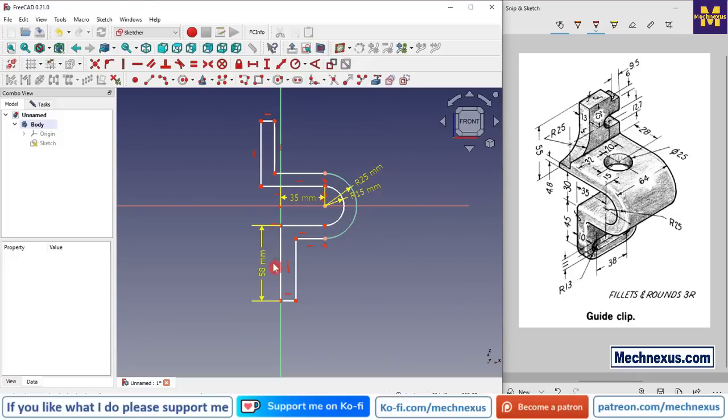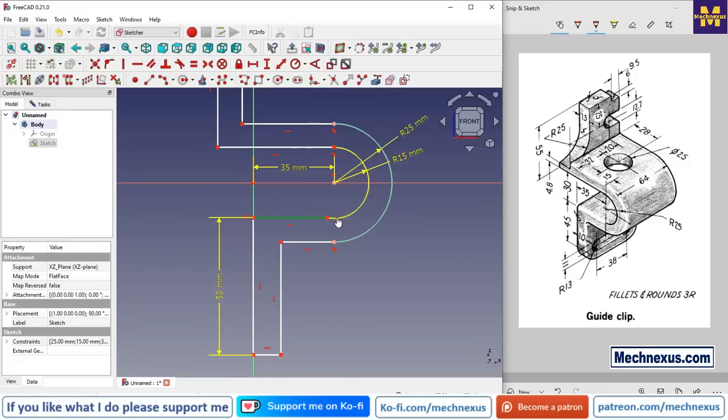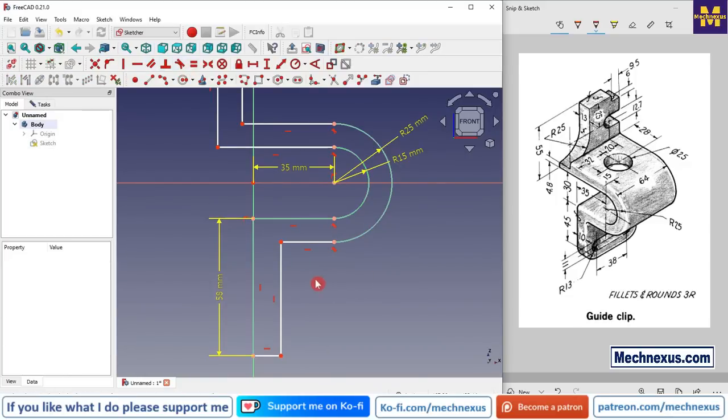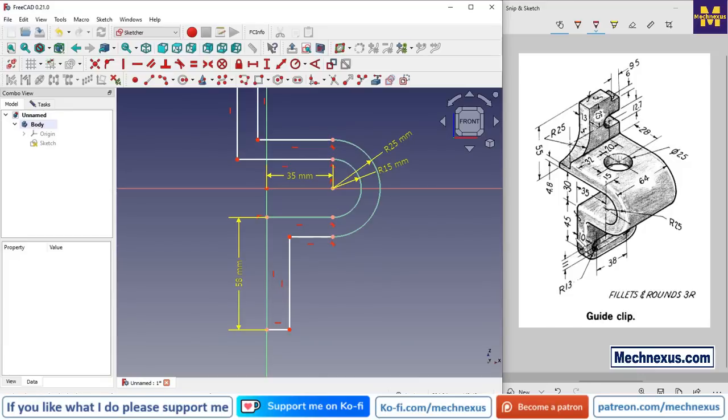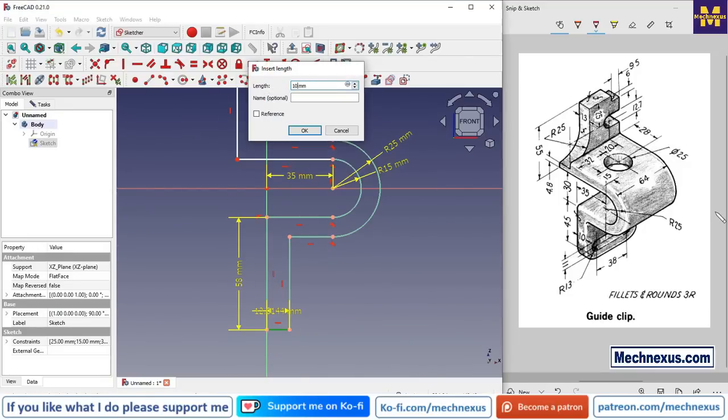And now we will constrain by moving what is unconstrained. So there is no tangency, so we will select and create the tangent. And here a thickness of 10 mm is given, so we will simply select this line and give the distance of 10 mm.